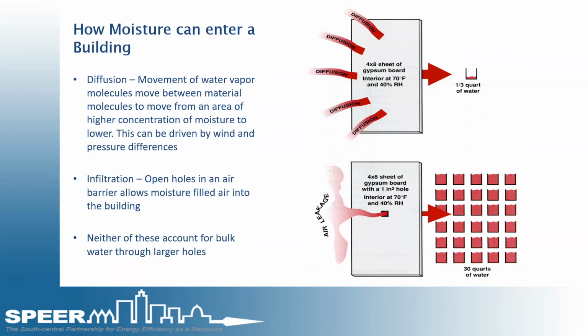So just having holes, that's about 100 times more important that you make sure these holes are sealed. Yes, it does seem petty. Yes, it does seem picky. But the accumulation of those, if you could cram those together and add them up, and they come to the size of a larger hole, like 1 inch, 2 inch, 6 inch. If you have that many holes in the envelope collectively, that's a lot of water that can be pushed through into a home.